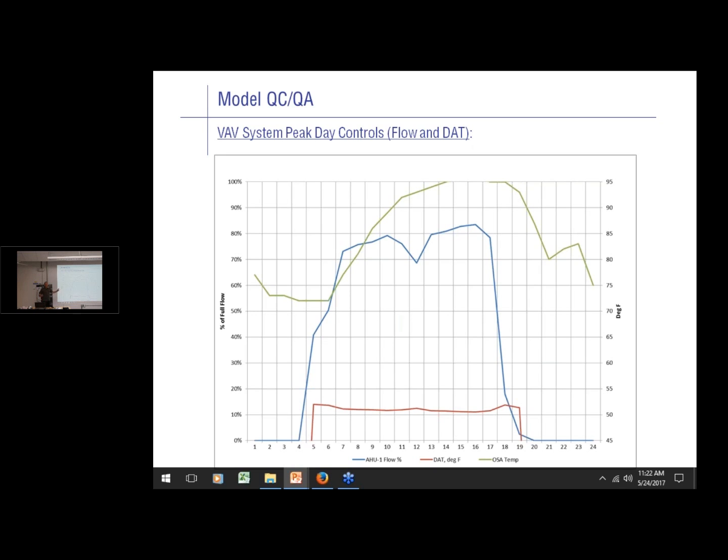So looking at the modeled discharge air temperatures in conventional HVAC system models is a critical thing to look at. Without looking at it in hourly reports in eQUEST and DOE-2, you probably have about a 25% probability of it being correct, if that. And these two work together, by the way. If this was up at 57, our airflow would be higher for the same load.